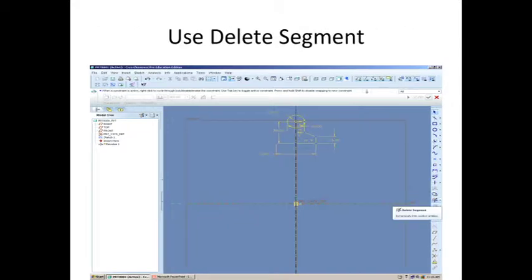Now we're going to make regular lines. I started off with the line at the very top going down 50, because that's the base of it. Then I'm going to go 35 to the right, and then up 15, and then from there I made a line at the midpoint going 15. Then I just connected the two endpoints to make that angle right there.